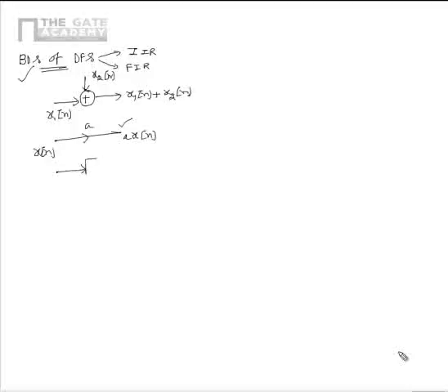There is a delay element that is also needed as a part of the block diagram, which is denoted as shown in the figure. It takes the input as x of n and the output of the same is x of n minus 1. The three symbols that we discussed just now are basic elements of the block diagrams. Let it be FIR or IIR filter, these symbols are very much used. Now let us start looking into the block diagrams of IIR filter.